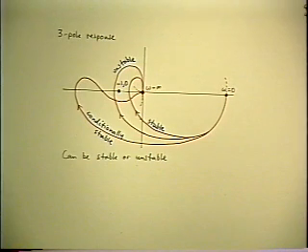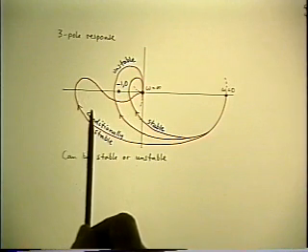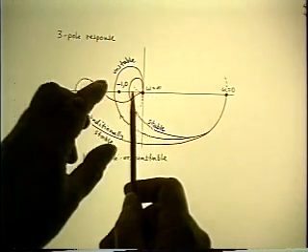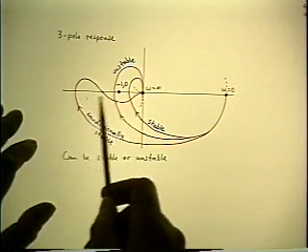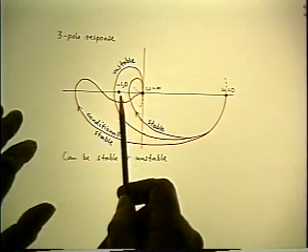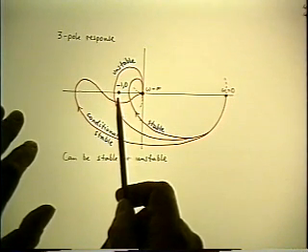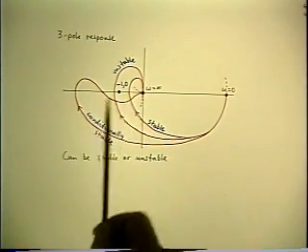And that's only one of the possibilities, because suppose you survived that and it did finally come up to the conditionally stable system and everything is fine, but then someone comes along and hits the output with an overload. Again, something saturates, cuts off, the gain drops. And the contour contracts, and again, it's going to be very difficult to ensure that it doesn't contract in such a way that it could go unstable again during the overload. And you could also be unlucky and it could get stuck in the overload condition. Even if you remove the overload, it may not recover because it's already oscillating and going nonlinear.